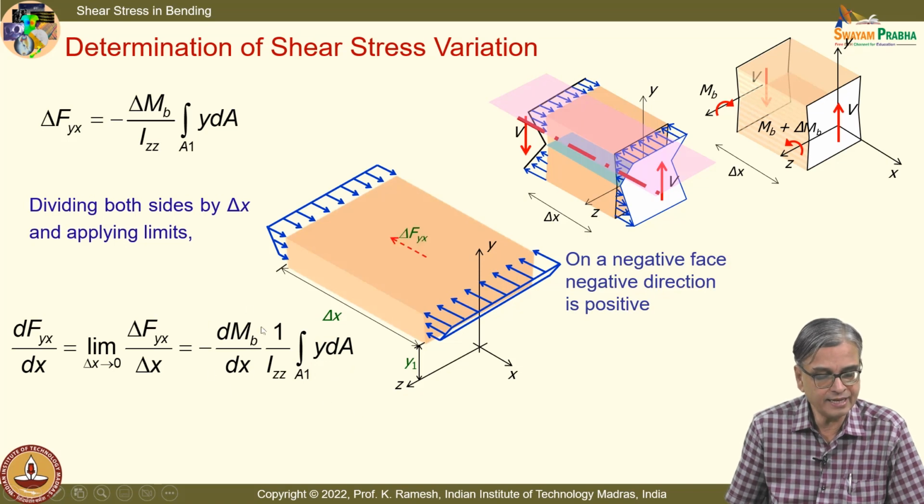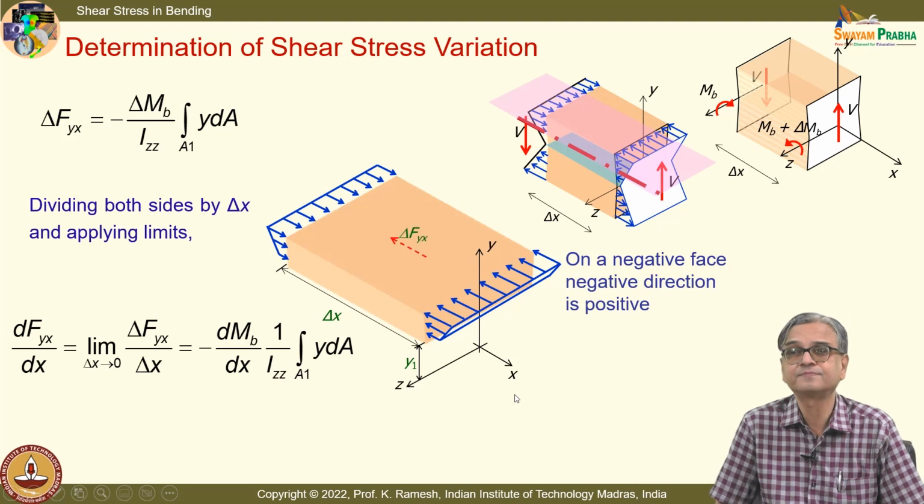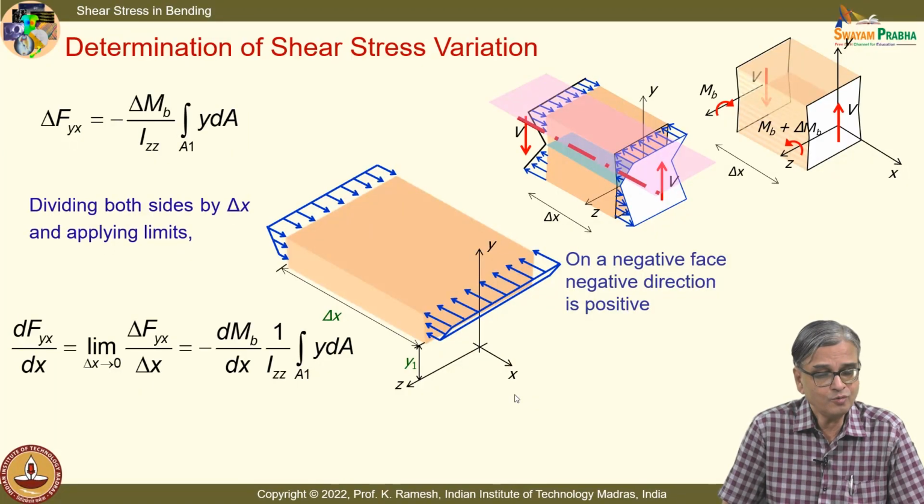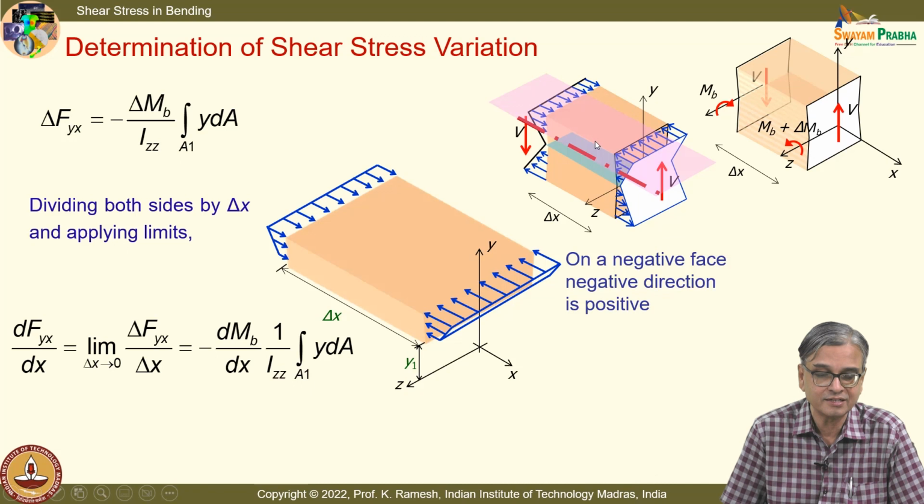Can you tell me how I can bring in the shear force here? Is there anything that you know from your earlier development of the subject? You can be louder. Equality of cross shears we have discussed, that is one idea, because what she is trying to say is, if I have stresses developed at the bottom surface, I should have stresses developed in this surface also. So, if I have this as x plane, I will have tau xy developed, and by equality of cross shears, whatever the tau xy developed, I will have tau yx, that is fine.